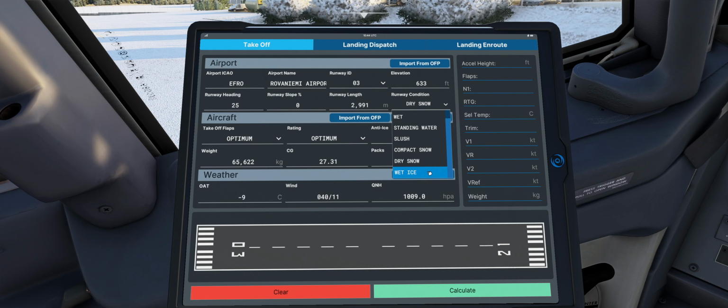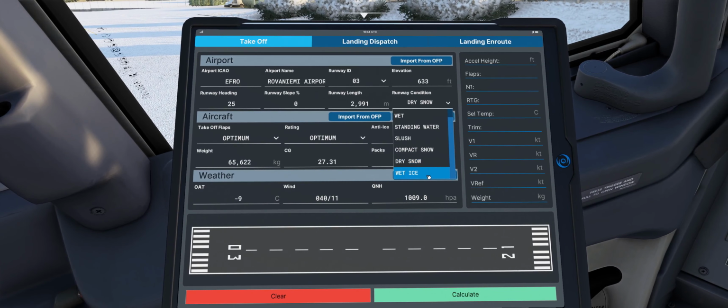but we are using the friction coefficient and we will specify what the braking actions are. So again, I'm missing the friction coefficient here, because in a real airplane and real electronic flight bag you have the ability to do it this way. But remember, when you have contaminated runways, these kinds of contaminants for the particular runway can decrease your maximum allowable performance limited takeoff mass by thousands of kilograms.